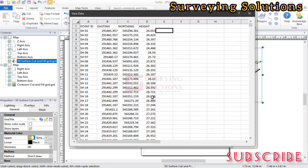With this range of height, we want to say that by design, we want our topography to get to 28, which means all of those elevations that are below 28 will be filled up to 28, and all of those elevations that are above 28 will have to be cut to get to 28, right? So the essence of opening up a spreadsheet of the data is for you to visualize the range of elevations we have, which will now inform our next surface, and the surface we are going to use now is 28. Please bear that in mind.